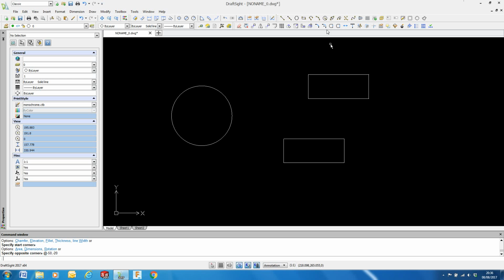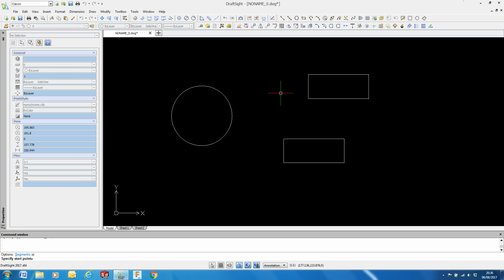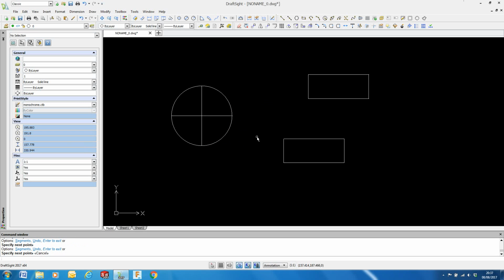just briefly whilst we're talking about our coordinate system. If I select my line tool, I have done, my start point, you will note I'm getting a snap location at 4 points of this circle, and I could draw lines between those points. I'm going to end the tool with the return key. I'm going to restart the tool with the return key just as a recap, and I'm snapping to quadrant points. I've just pressed the escape key to close the line tool. So quadrant points are positions on a circle where a vertical and a horizontal line cross that circle. They're quite useful points for drawing with.